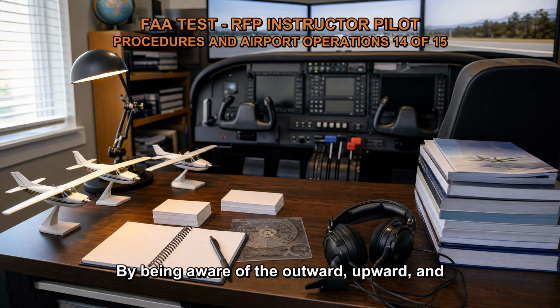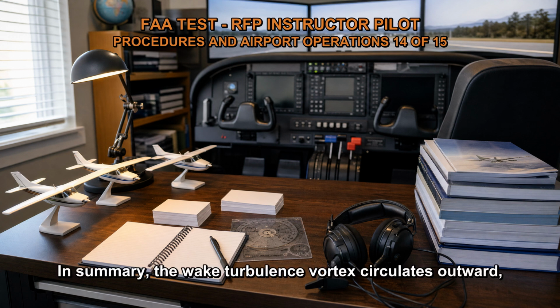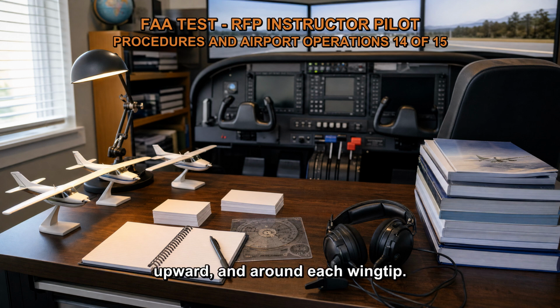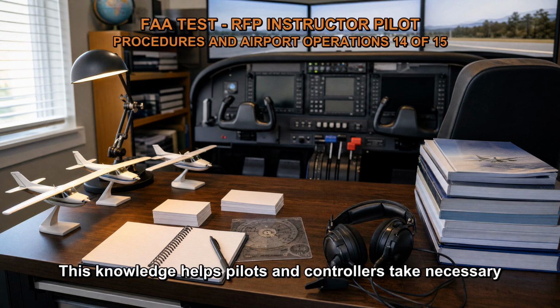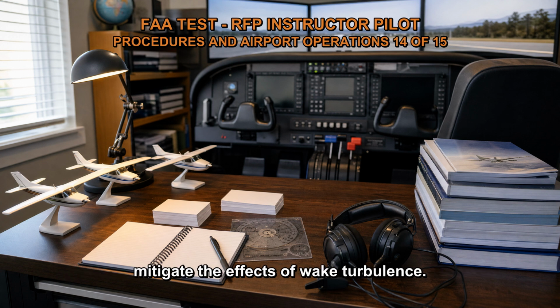By being aware of the outward, upward, and around circulation of wake vortices, pilots can adjust their flight paths and maintain an appropriate distance to minimize the risk of encountering turbulent wake disturbances. In summary, the wake turbulence vortex circulates outward, upward, and around each wingtip. This knowledge helps pilots and controllers take necessary precautions and maintain safe spacing between aircraft to mitigate the effects of wake turbulence.